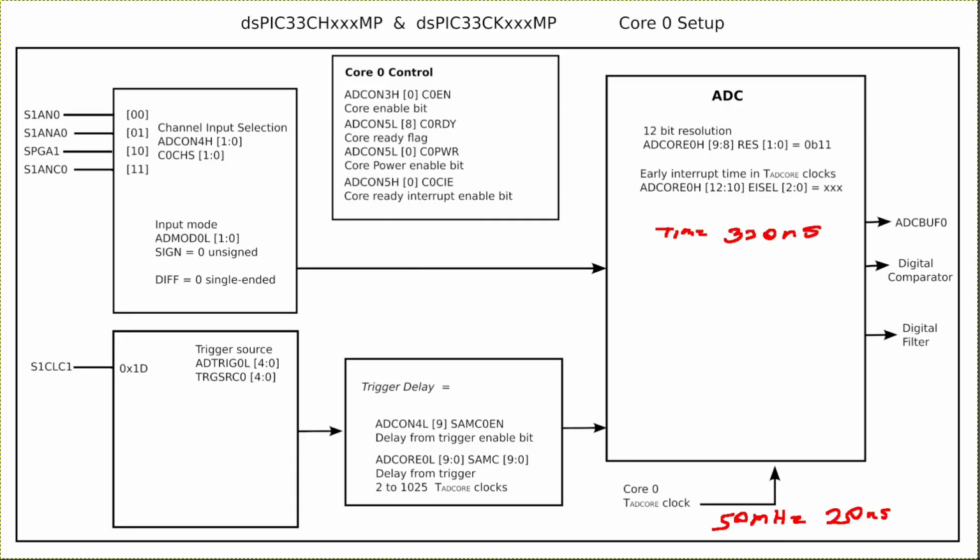Probably even overkill. But for now, I'm going to trigger the ADCs at just over 120 kilohertz. I'm going to set the filter at 4x averaging, so most of the ADC time will be spent in the sampling state. I'll adjust the conversion delay register to try and equally space the 4 samples in between the 120 kilohertz triggers. And if this turns out to work okay, I can come back and lower the ADC clocks to save some power.